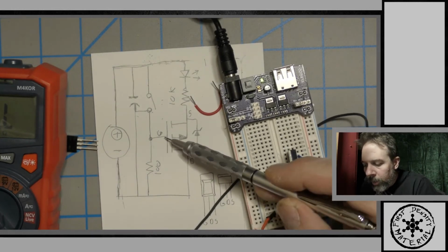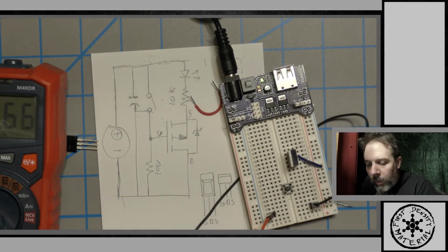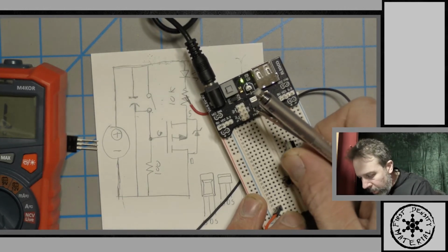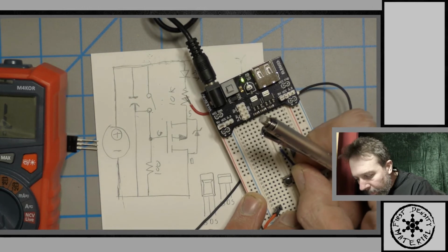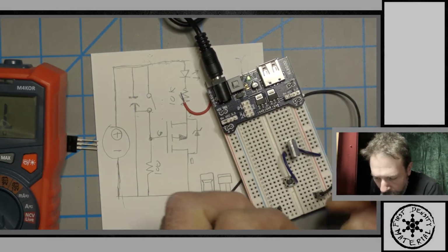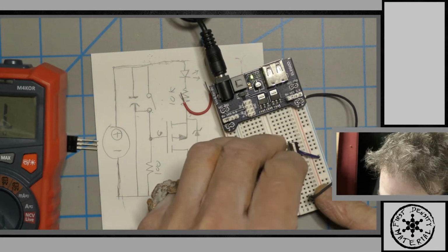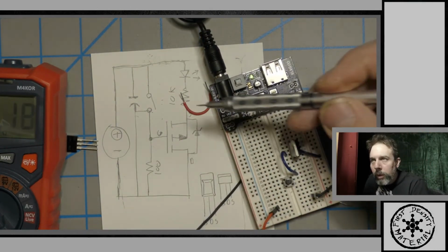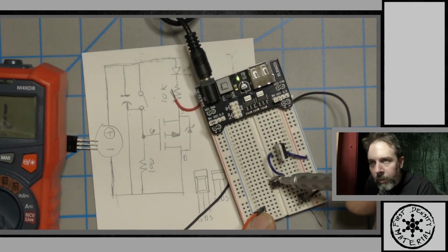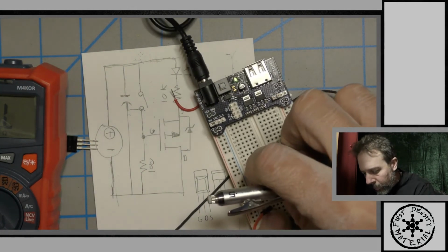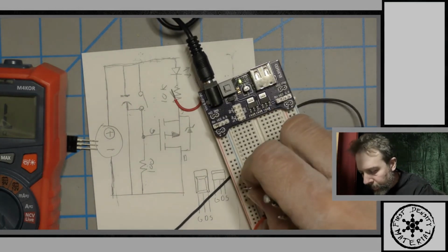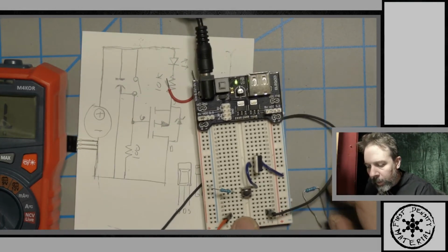We're looking at the 100K hooked up to the G. But it was hooked up to the G through the switch. That way it saves some breadboard. You don't have to do that, but in this case I'm going to hook it up to the switch. So the gate is going to be hooked up to the switch, this one right here. So I'm going this way first. And since the switch has a passive, where's the resistor going? It's going into negative. Just like that.